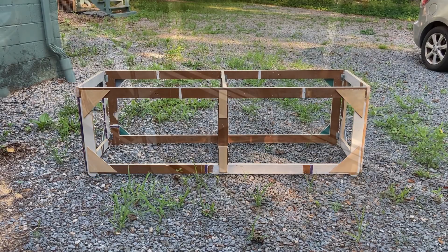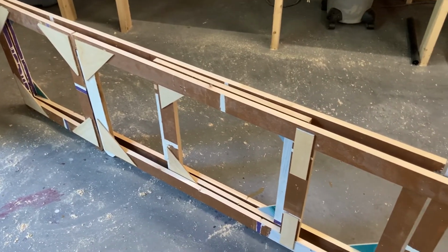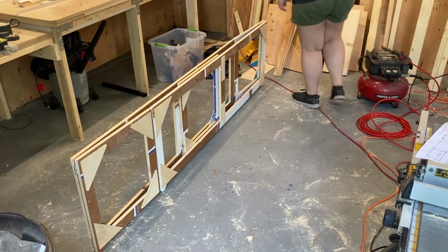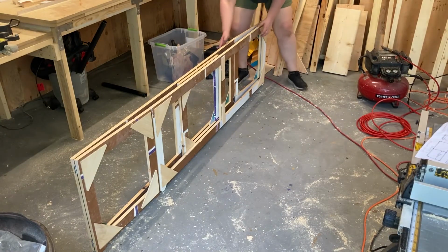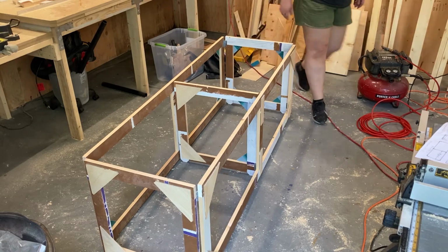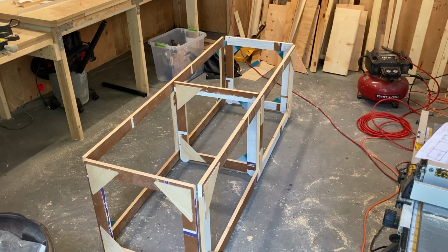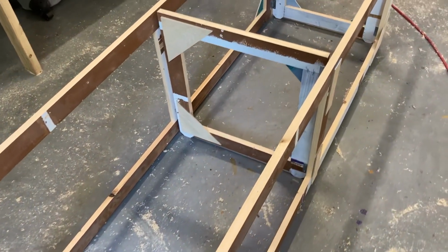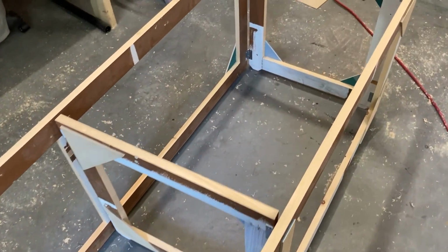Now completed, this parallel frame can be used to safely support an individual platform. If I were to make a plywood lid, this would create a 2-foot by 6-foot platform at a height of 24 inches. Collapsed, the frame is under 3.5 inches thick and can be stored in narrow areas. It can be set up in a matter of seconds and is very lightweight. For transport, parallels can be secured in their collapsed position using tie line or straps of Velcro.